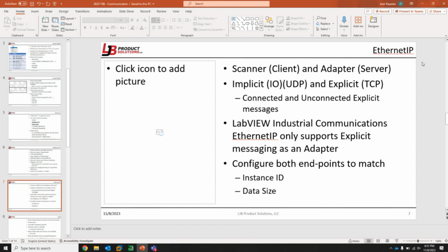So, yeah, that's what we found. The first thing we did, well, I don't want to say the mistake, was we bought a Rockwell PLC and got a license for Studio. Spent a ton of money basically to turn the PLC into the middleman so that our LabVIEW application could talk to a servo drive. Then once we learned more, we went that route and used a much less expensive CPU, free programming software, and got the exact same performance out of it.